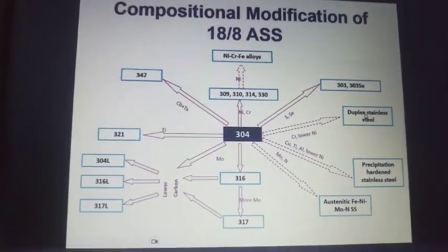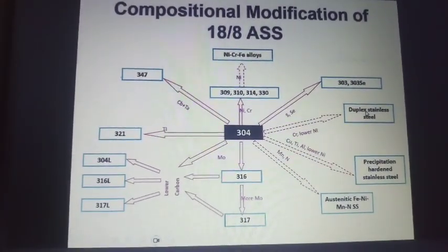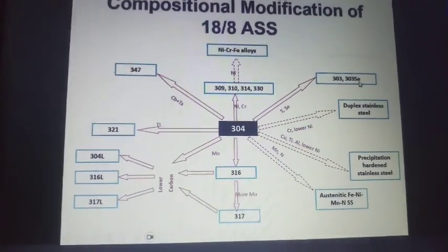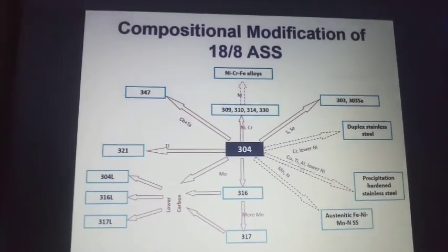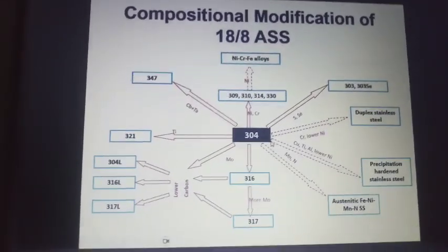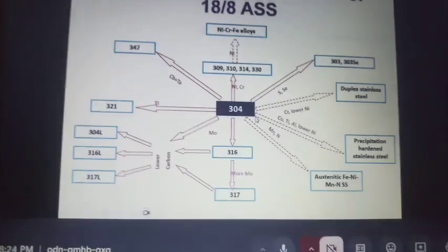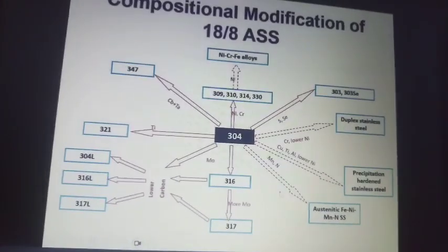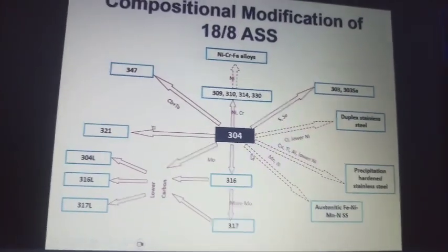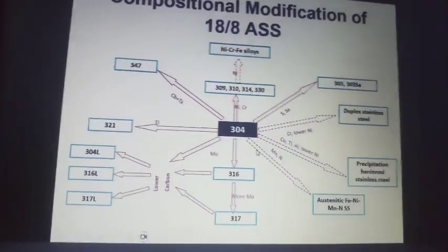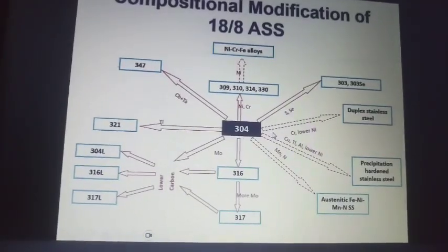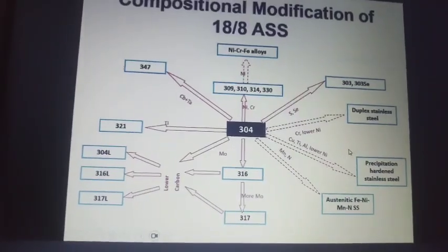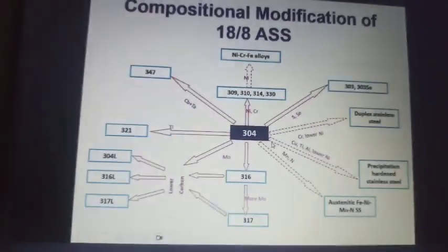Or super duplex. Super duplex also comes in the same family, right? Super duplex is again in the family of duplex. We call it super duplex. I think super duplex is 25% chromium, right? Yes. The word super comes when it has a minimum PREN of greater than 40, then only it is super. Not because of chromium, it's because of the PREN value.